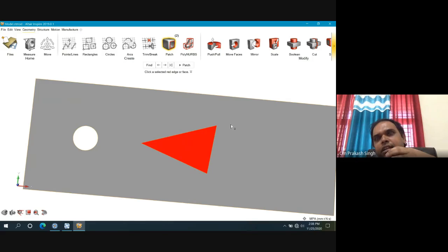And you have more than 2 regions. So earlier it was 1 region, now there is a solid region too. Fluid and solids should connect through an interface. There is a special treatment in CFD to model the interface. So you define the interface, then you can model the inside of the object also. If that is not the part, you just subtract it, remove it, the impression.